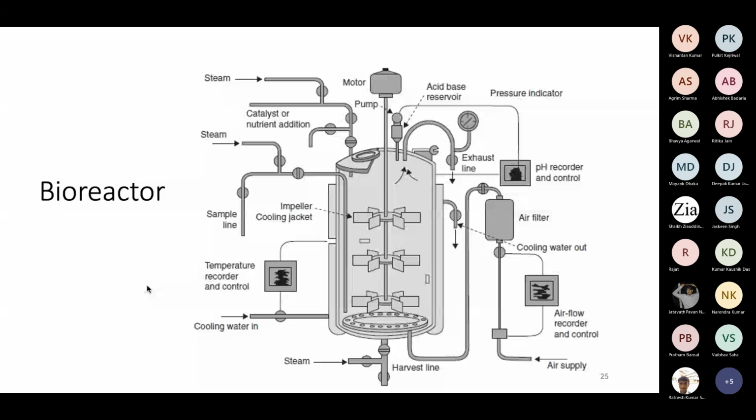So typically on the head plate you can have this stirrer shaft hole, and generally in the stirrer shaft hole you will use some mechanical seal to avoid any leakage of gases. So outside gas should not enter the reactor. So although it is not shown here, but you will have mechanical seal. And on the top you will have motor shaft.